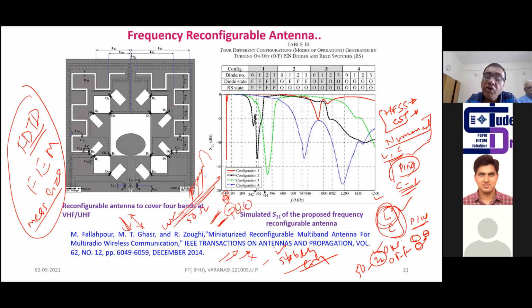But if your results are changing and we get a new result every time we change the boundary conditions, that means your numerical results are not stable. It has to be fixed, and the stability characteristics will be fixed by reducing the mesh size. The condition is that you have to reduce the mesh size forcefully. Now, how can you do this?